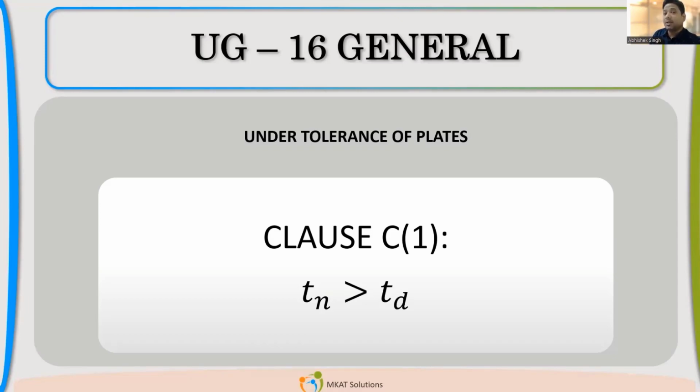Within that range, you have to fabricate. The fabrication cost also depends upon these tolerances. If the tolerances are in microns, your manufacturing cost will be much, much higher. If it is a general tolerance of plus minus 1, 2, you can achieve it by fabrication. Machining may not be required. But that also depends upon how much length we are talking about.